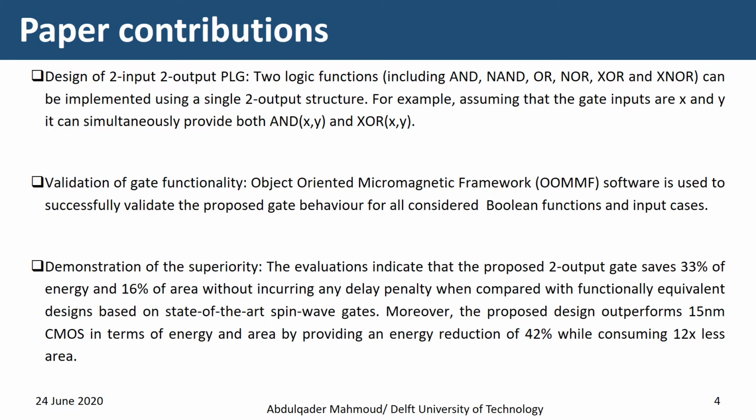The contribution of this paper can be summarized as follows. Design of a two input, two output programmable logic gate. Two logic functions, including AND, NAND, OR, NOR, XOR, and XNOR, can be implemented using a single two-output structure. For example, the gates AND and XOR can be implemented at the same time for the same inputs.